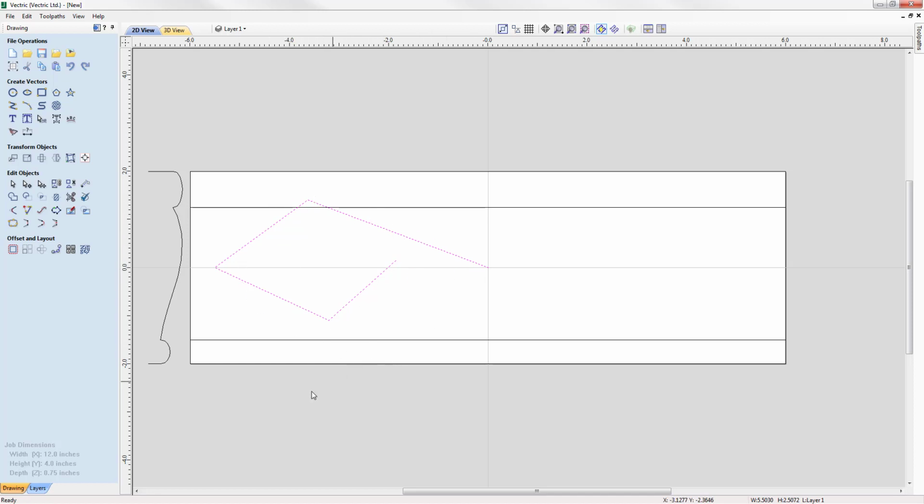So to really transform this shape, we're going to put it into node edit mode, which is this option here. Okay, now I want to look at smoothing this point, and this point. So to do that, I'm just going to box select those nodes like so, and then press S on the keyboard in order for me to smooth them. And so with all of those nodes smooth, you can see we're presented with all of these handles, and these handles enable me to really transform the shape of the curvature that we're going for.